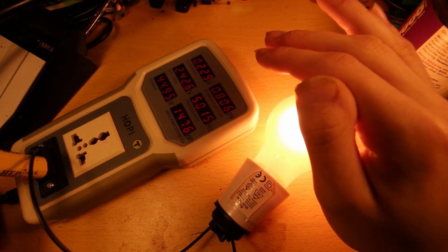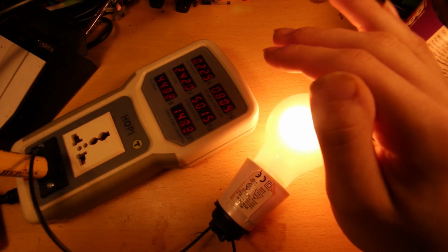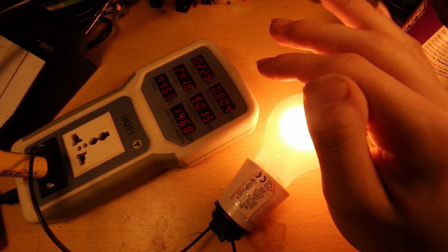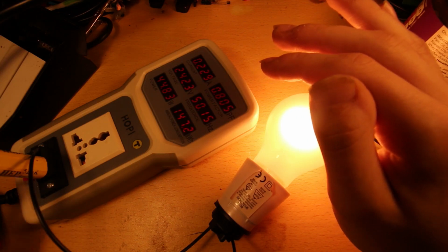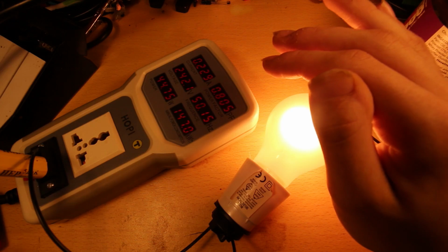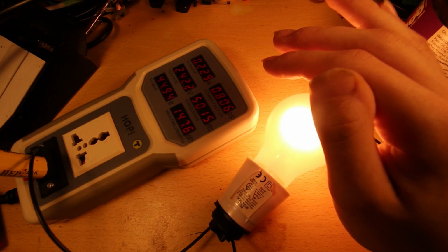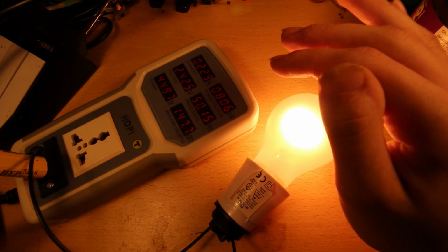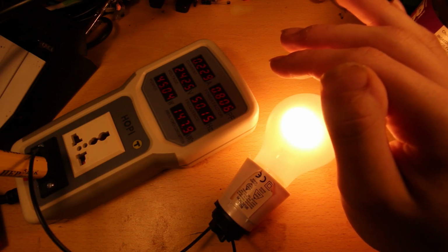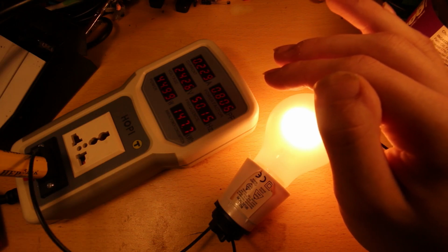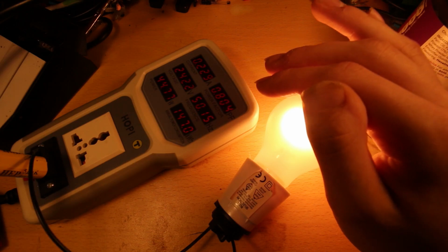The capacitive reactance of this capacitor, I don't touch it because it's live, is 636 ohms, which means this is equivalent to a 636 ohm resistor. However, a 636 ohm resistor would be dissipating 83 watts if we banged it straight across the mains. The actual volt drop across this capacitor would be less, so the actual dissipation from it would be less.